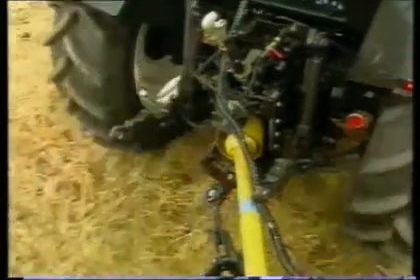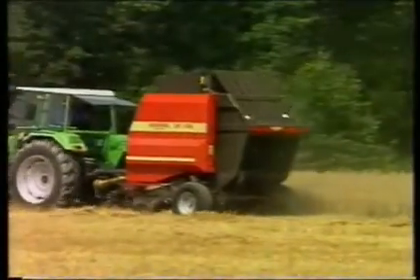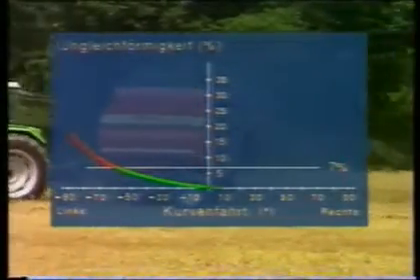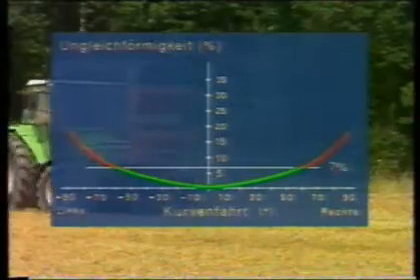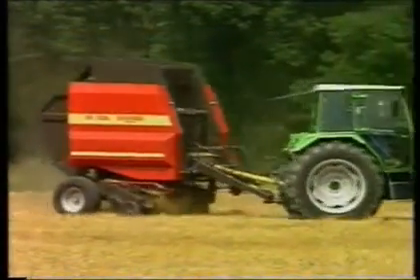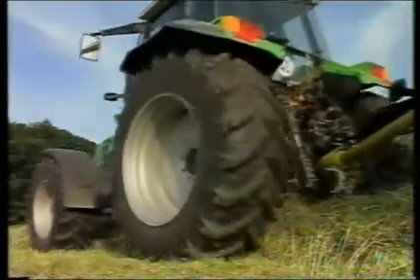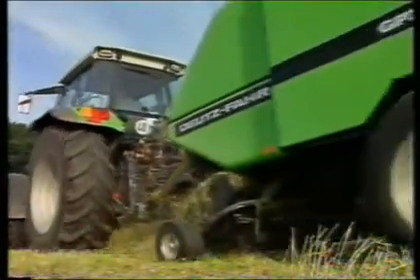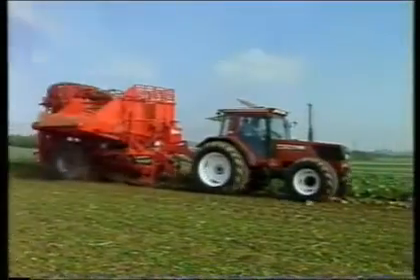The additional forces on the end yoke reach a maximum at a defined rotary angle of 0 degrees or 180 degrees. At increasing rotary angles, these forces decrease to 0, while the forces on the inboard yoke increase and reach their maximum at a rotary angle position of 90 degrees or 270 degrees. Thus, the additional forces are not constant, but fluctuate periodically twice per revolution.